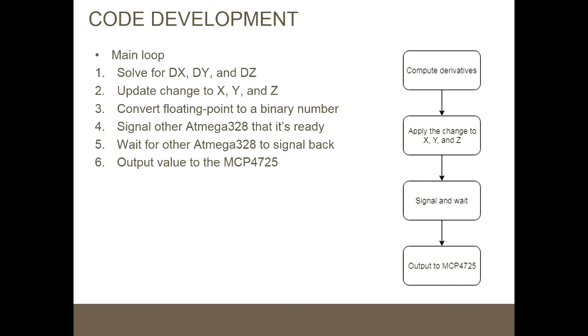Now, what I did to get this floating point was convert it back from the floating point to a binary number. Since we have a fractional part, how do you represent that in binary, and how do you output it to the DAC? The DAC is a 12-bit DAC, so you get 4,096 integer numbers, and it definitely does not take binary floating points.